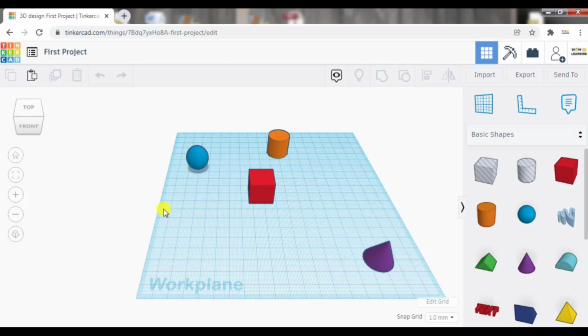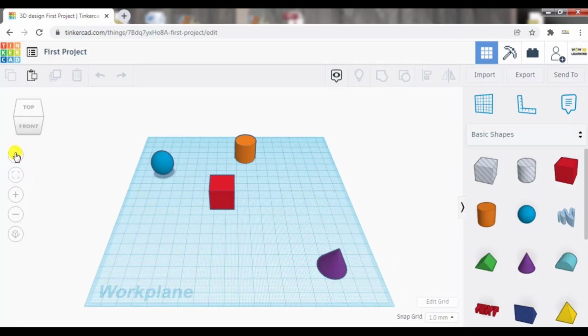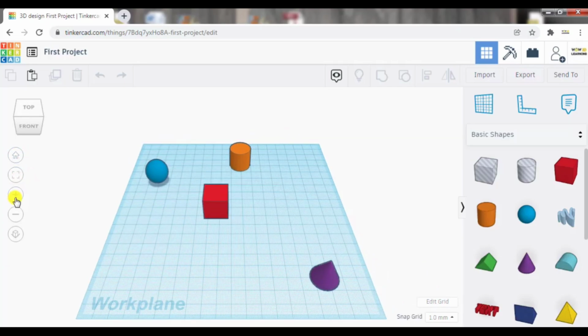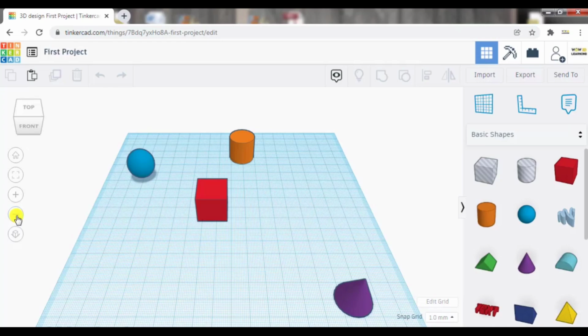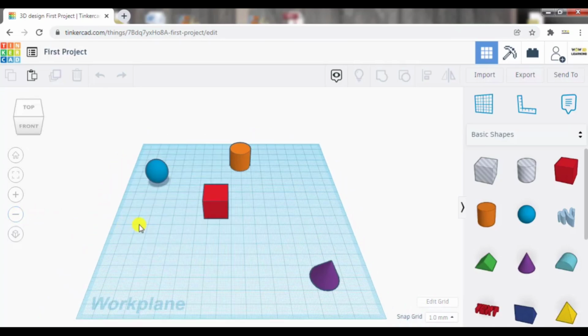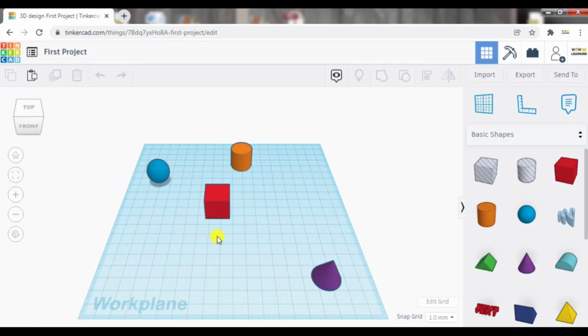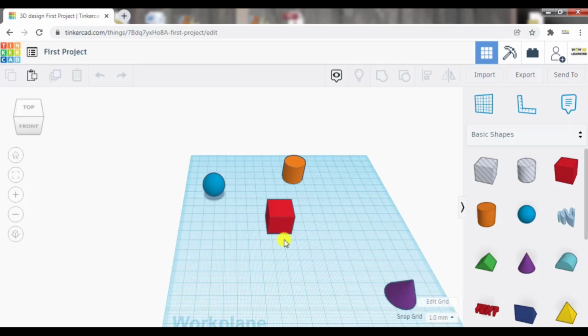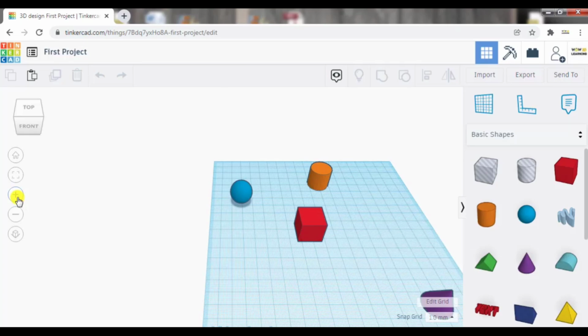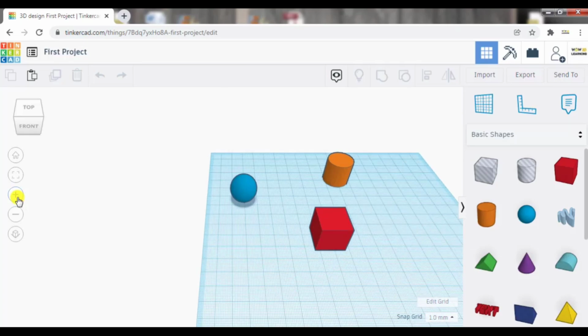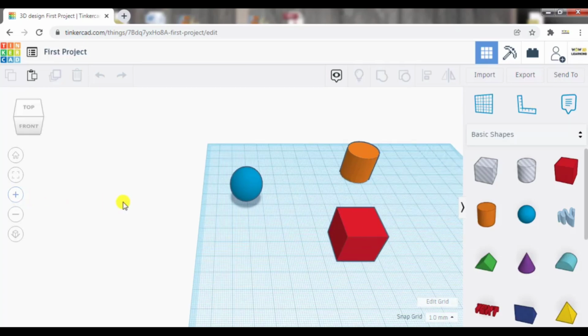The benefit of panning is that if you remember we had talked about zoom. Whenever I press zoom in, it always happens with respect to the center of the work plane. But with the help of pan, it is possible to change my focus to another object of my interest. And now if I press zoom, you can see I am focusing on the blue sapphire.